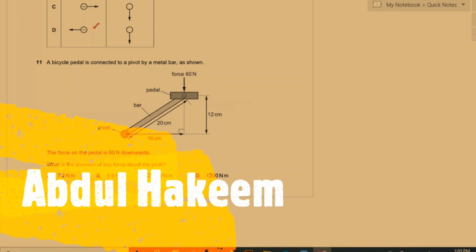Move to the next. A bicycle pedal is connected to a pivot by a metal bar as shown. What is the moment of this force? Look, this is the line of action of the force, 60 Newton. And the moment is force multiplied by perpendicular distance. So the perpendicular distance is 16.